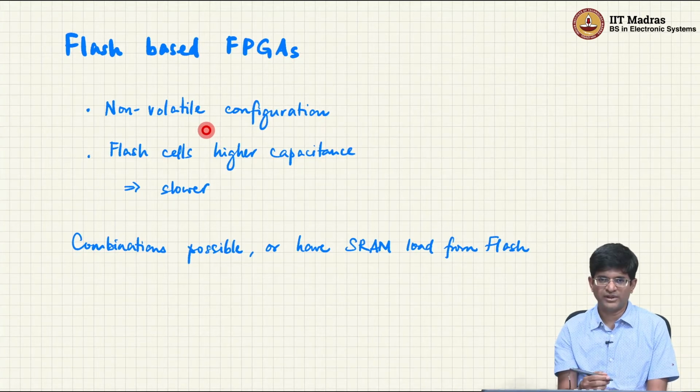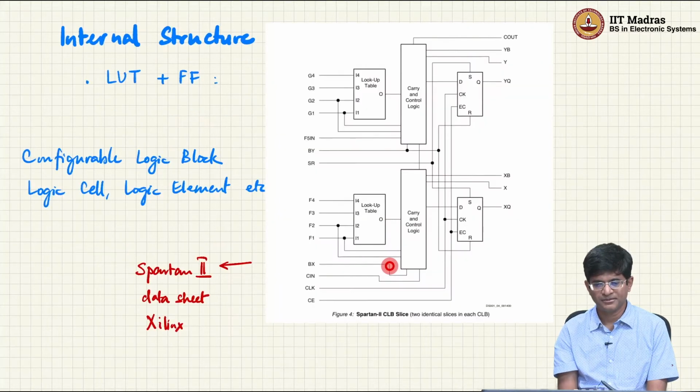So you could also have different combinations of these. For example, you could have SRAM based FPGAs, but which as soon as you switch on the system, they basically load their configuration from a separate flash memory, right. So people have figured ways around this, except that now you need 2 chips on the board, so it's always a trade-off. This is how engineering works, right.